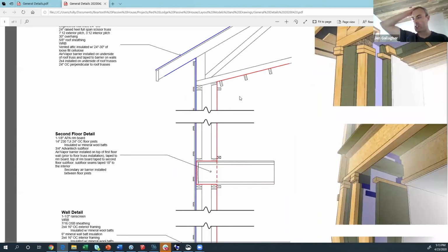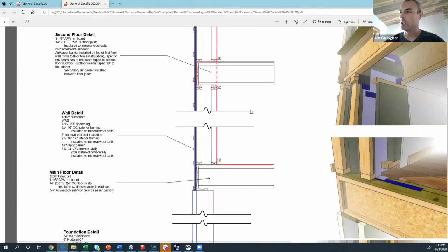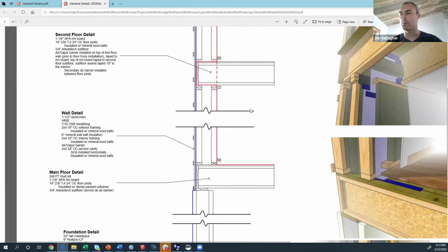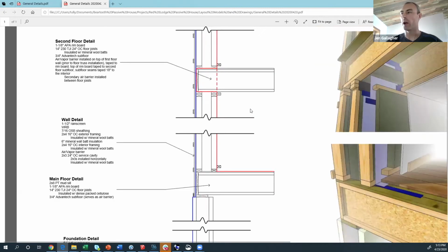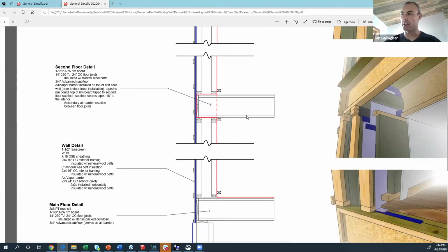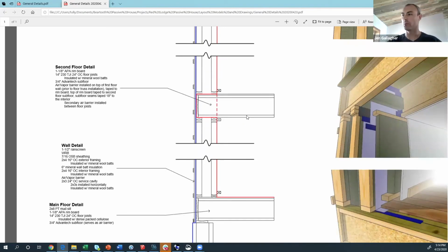Some people had asked, why double stud? So there's as many ways that you can dream up to build a fat, big, thick wall that is higher performing. However you want to dream it up, you can do it. And I don't think there's any one right way. There's trade-offs one way or the other. So double stud for us was really easy because, like I said, we were partnered with EMU. That's their construction system for Climate Zone 6. So I didn't have to think about it anymore, which was awesome. I just said, okay, how do we do this?